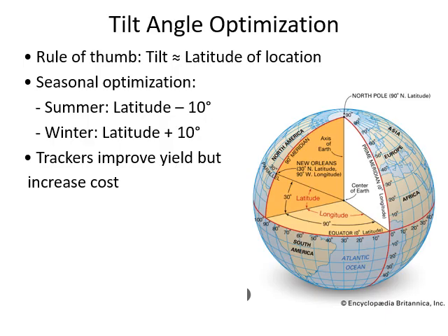Okay, now we are going to have a look at how we can optimize the tilt angle, like at what angle we should place the PV panel to capture the maximum solar irradiation, right? So the rule of thumb is the tilt is the latitude of the location. So you have to tilt it according to the latitude of your place. I believe Gaza is at 31 degree latitude. Latitude is, by the way, the horizontal line across the earth. So these are the latitudes.